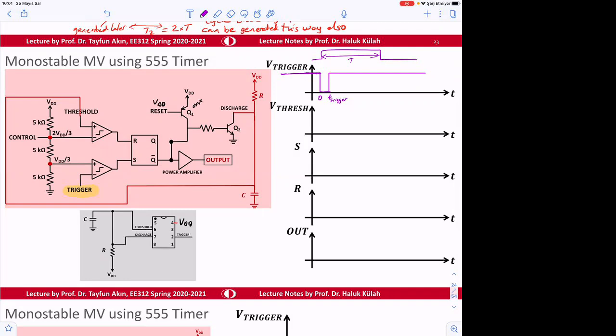In order to understand where the circuit is staying, one thing is to assume that the capacitor is maybe an open circuit, or the capacitance is 0. So analyzing and finding the initial states is not going to be straightforward maybe, but the best way is to assume something and then see if everything is satisfying that assumption.